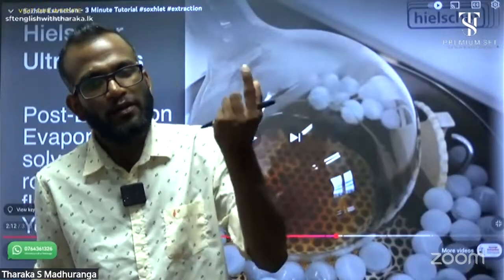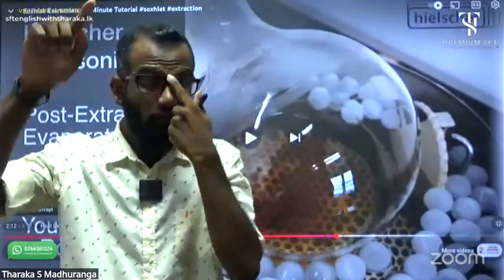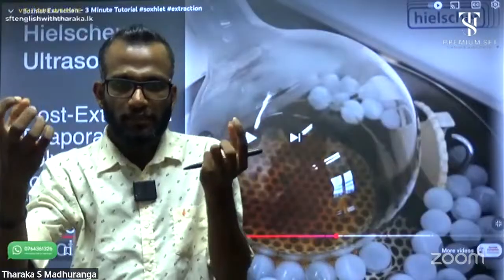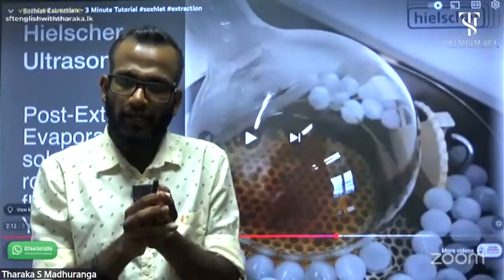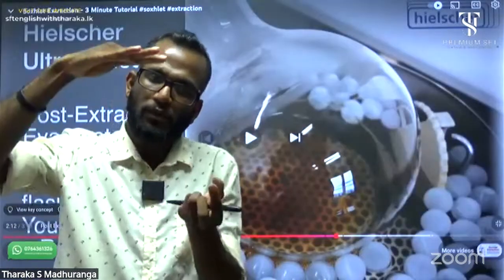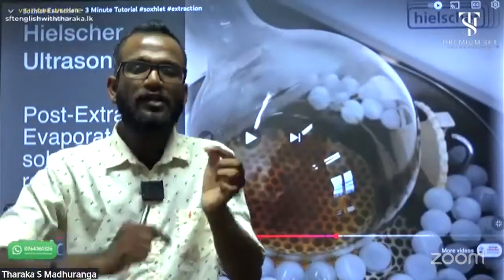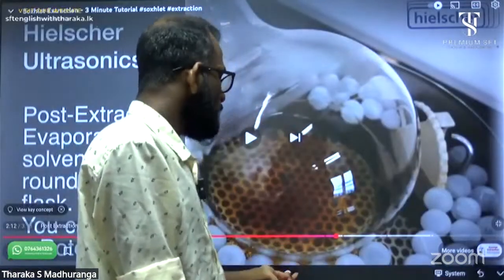Solvent vapor evaporates and the vapors transfer to the condenser, and this condensed liquid again fills into the plant material container. When it is filled up to the siphon tube, it is siphoned into the solvent chamber again. This process continues continuously. That time period also depends on the plant material.